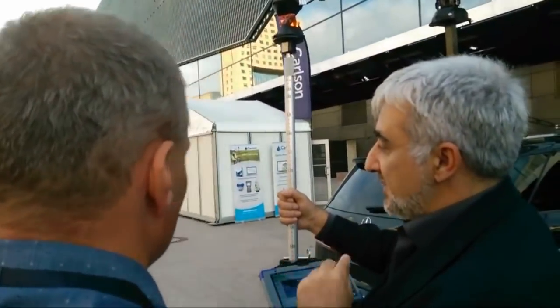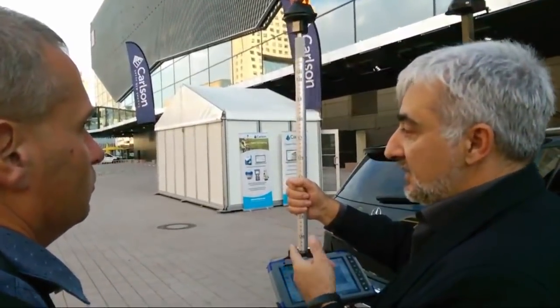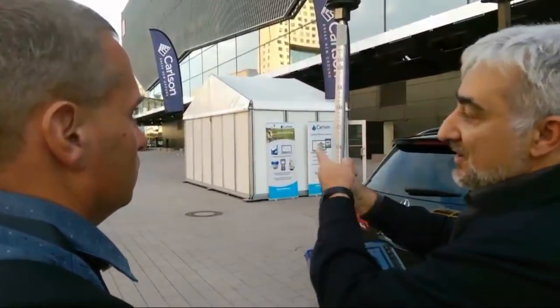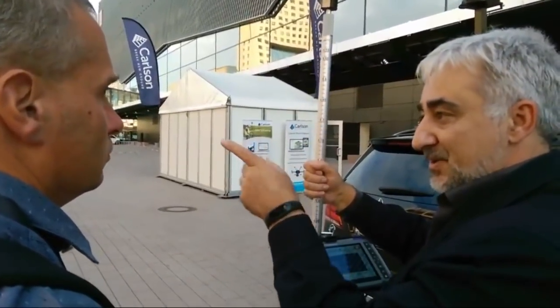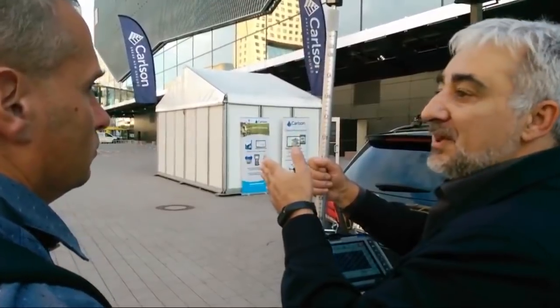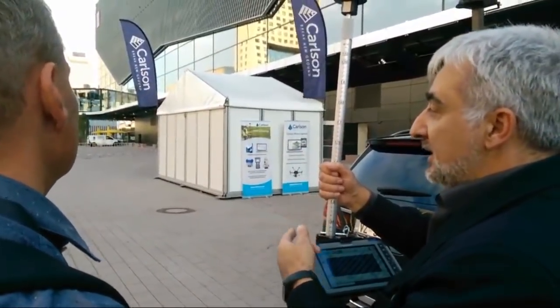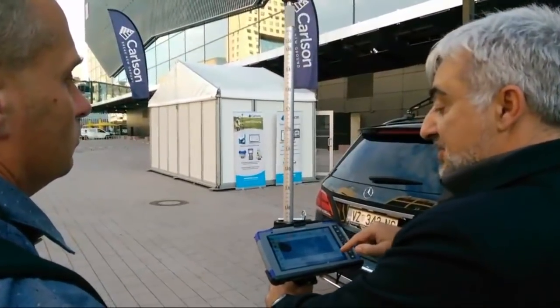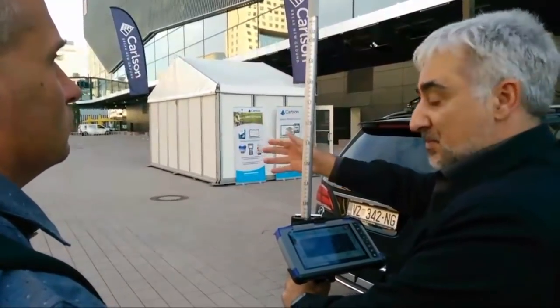It works a bit differently if I am in stakeout. If I stake out a point, then it knows where I'm going, it knows my target. I have to go to the point to stake out, and Survey Pro knows where the point is. So it tells the instrument, okay, aim to the point and wait for me. So if I stake out a point, it will turn to the point, wait for me, and give me position with the GPS to get to the point. We can reproduce it if you want now.